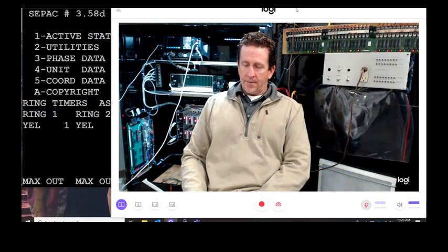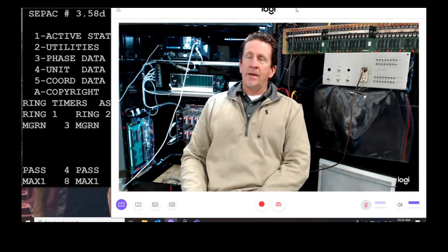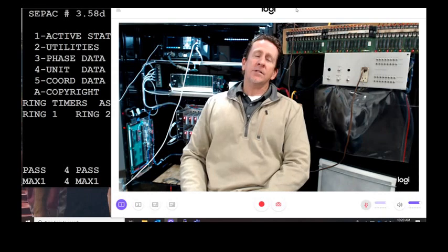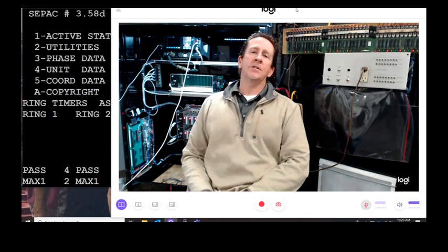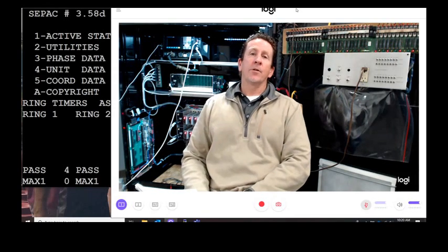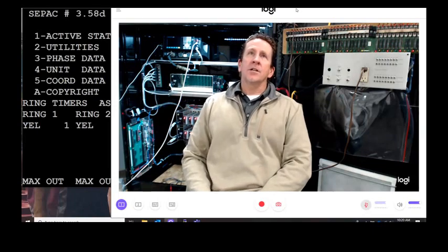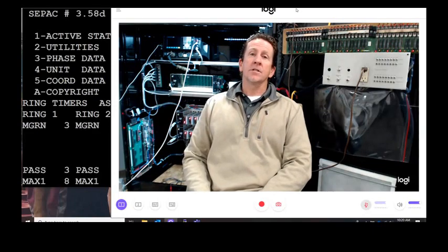And then the other main thing you do, if you can't do anything else, there's nothing worse than having, actually, this could go two ways, because some agencies would prefer this. If the intersection is dark, typically the first thing we want to do is everybody says, let's get it flashing.